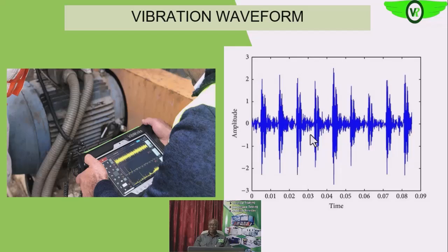It may be able to give you that, but you have a better understanding of what is happening if you have been taking your vibration readings and carrying out vibration analysis regularly before, so that when the equipment is good, you analyze the waveform and the spectrum to identify each of the forcing functions in that electric motor on the spectrum.